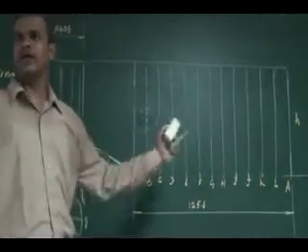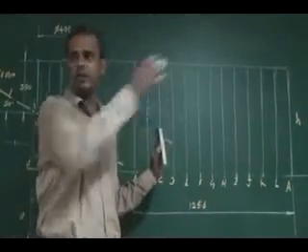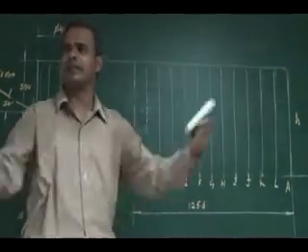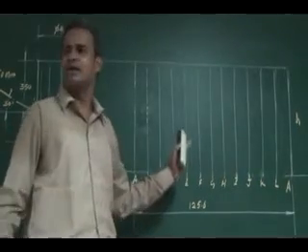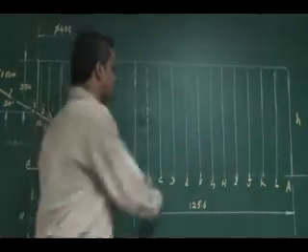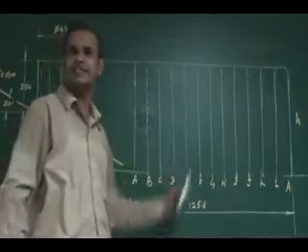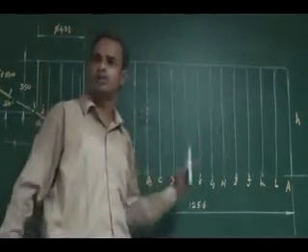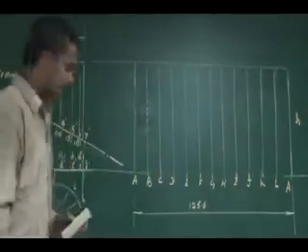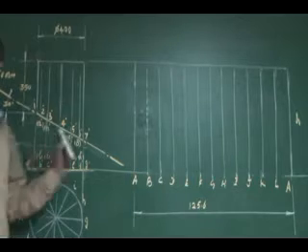Listen. So actually it is a sheet. Development of a cylinder is nothing but a rectangular sheet. I can form a cylinder, right? So these generators will not appear in your sheet, right? Just it should be in 2H pencil to mark the locations of those points of the circumference, right?